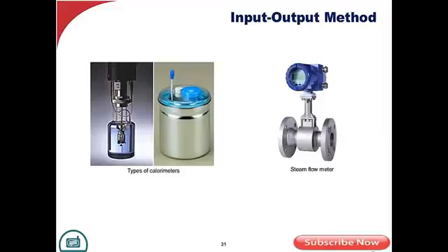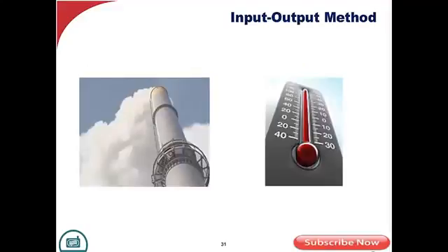And then, of course, I look at stack temperature, I look at the constituents of the gas, I look at my dry gas temperatures, I look at the moisture losses and so on. That all goes into the input-output method. And even though it can be very, very precise, it requires a lot of labor, instrumentation, and a lot of complexity. We've found over the years that probably the best and most efficient way to go about this is just the heat loss method. What this does is it takes into consideration what the stack temperature is above the saturated temperature of the boiler itself.